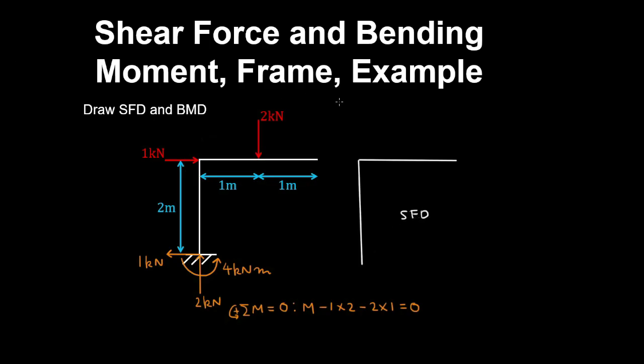And I'll remind you of the convention that we use when we cut the beam and the column. So I'll draw those in quickly. And we rotate this positive sign convention for the beam anti-clockwise to get our positive sign convention for the column. So if we cut the beam from right to left, we use this convention. And we can see that the shear force is 0 up to the point load.